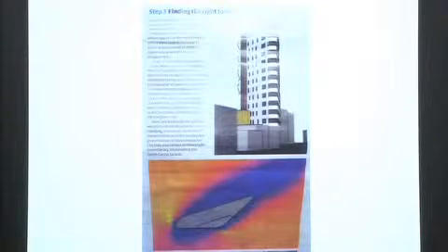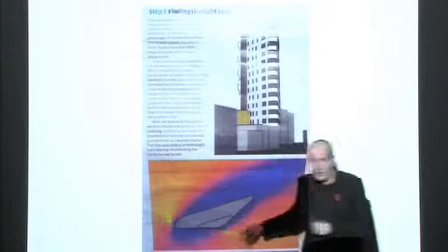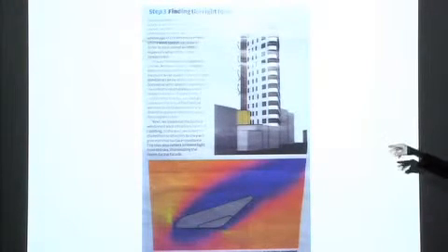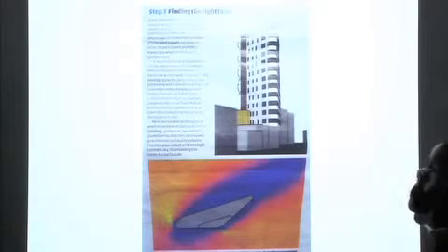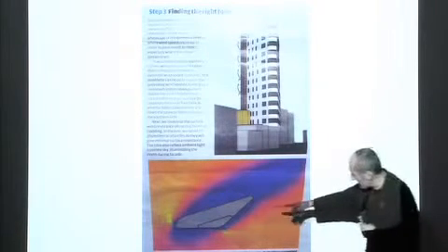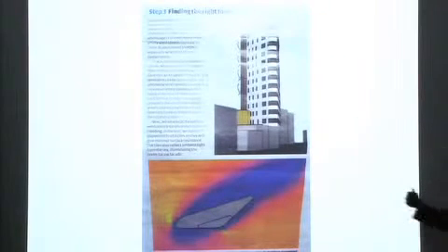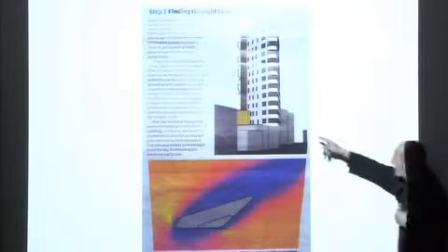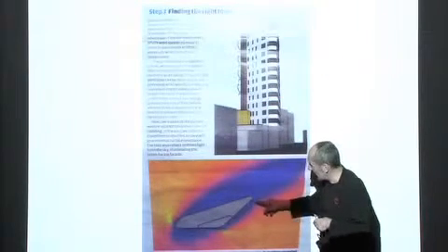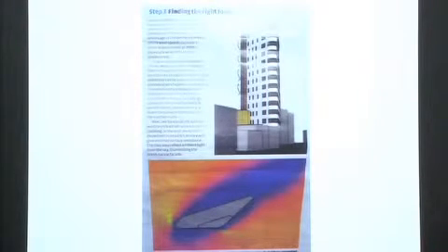Using that analytical software here, this building was designed on plan as a kind of aerofoil. Given that they did want to power it by wind generators, what's the most efficient way of doing it? By designing that particular horizontal section through the building, I can exaggerate the movement of air around the building. So if I pin my, in this case, helical generators on the tail edge, I'm going to get more air working around them. I think if you are going to do it, that's a nice bit of analysis.